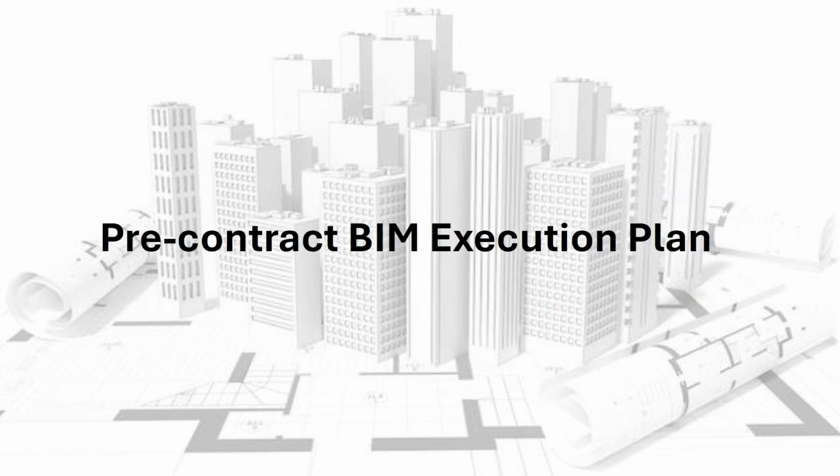For now, we can check a pre-contract BIM execution plan, BEP, content. A pre-contract BIM execution plan, BEP, is a document that outlines the client's or project owner's requirements and expectations for building information modeling, BIM, on a construction project. A typical pre-contract BEP includes project overview and objectives, BIM scope and deliverables, BIM standards and protocols, data management requirements, collaboration and communication expectations, BIM-related roles and responsibilities, and evaluation criteria for tenderers' BIM submissions.